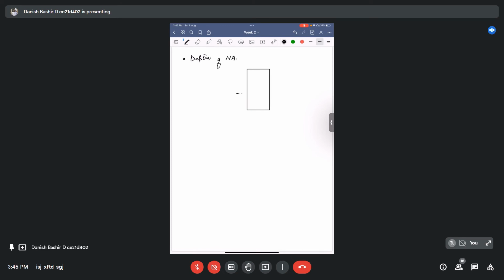If we assume, for example, that our neutral axis is at this point, and we want to know the location of this. This area is AT, not the gross area AG, it is the transformed area AT. And we say that the neutral axis depth is y bar from the top fiber.